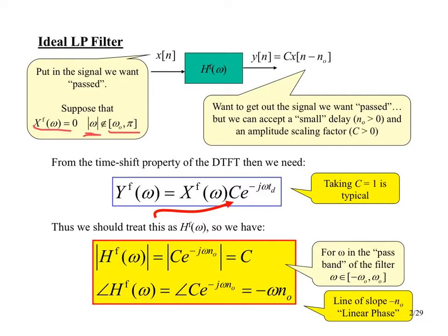So, even though we're not talking about it here, presumably there is some undesired signal that lies in those frequencies where the desired signal is 0. So we'd like to pass the signal through the filter and keep these desired frequencies, but get rid of the higher frequencies where there's presumably some interference or some noise. So that would be the ideal setup where the undesired stuff is in a band outside of the band where the desired signal lies.